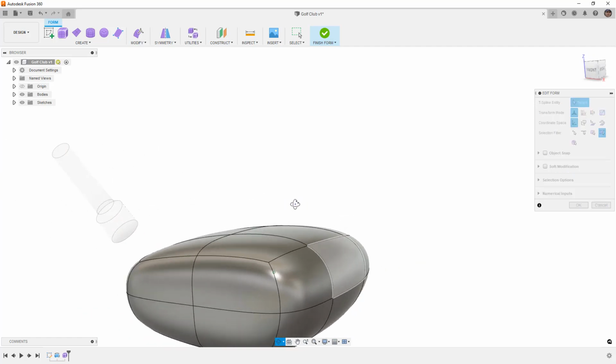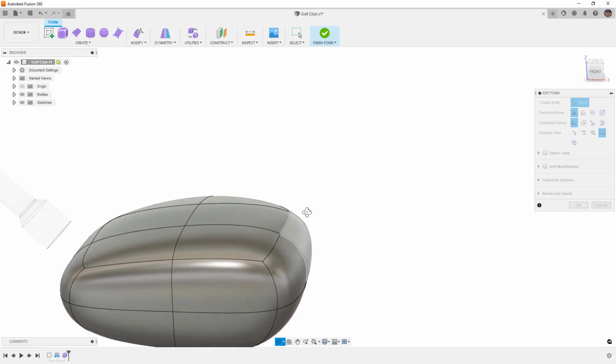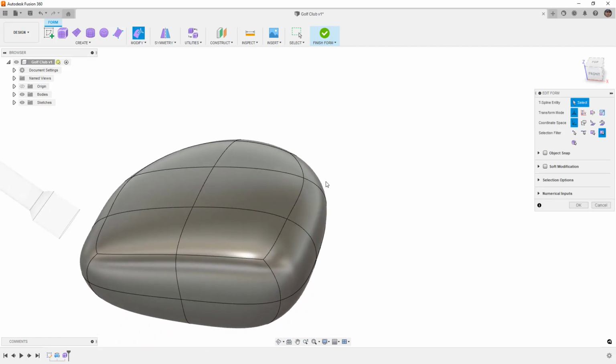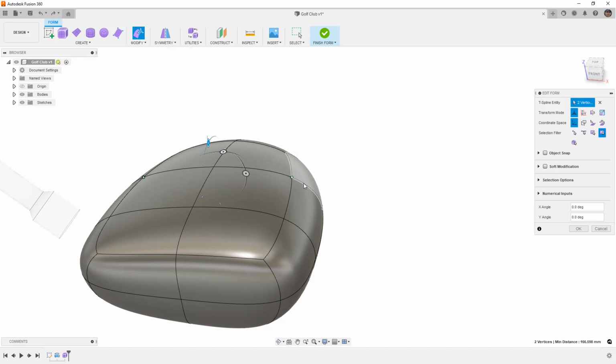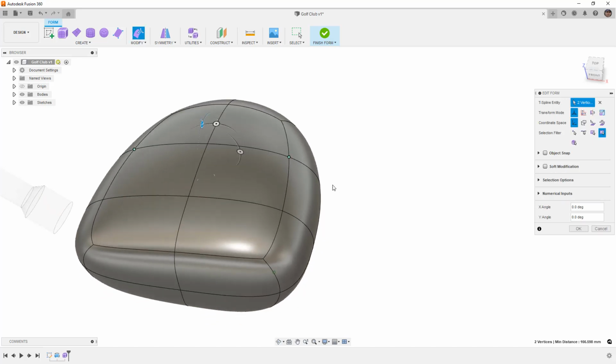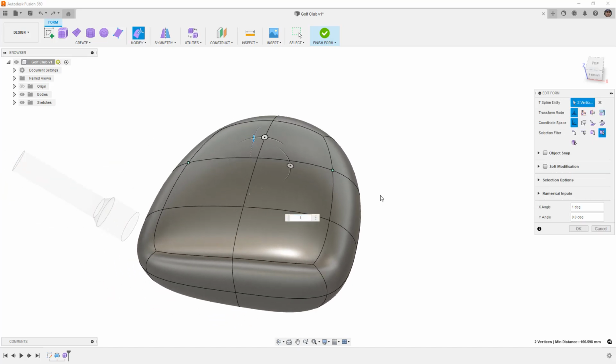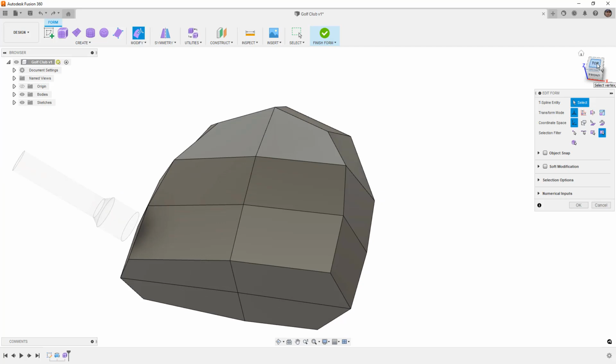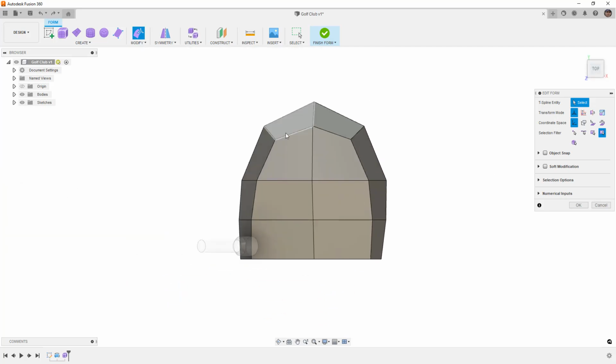And you don't generally see this in smooth display when you don't have a high level of detail, but it is going to be very apparent in the final shape, especially if you start subdividing this thing. You'll notice that you start to have some issues with the curvature. So we want to be very mindful when we make these changes. We want to do just these gradual changes, try to keep the edges parallel or slightly converging or diverging. You don't want a very drastic change.